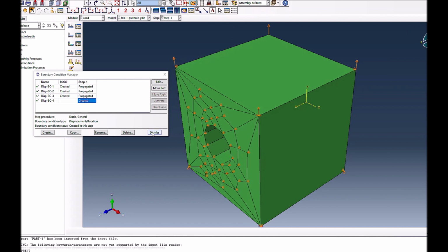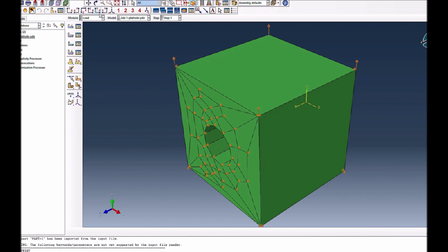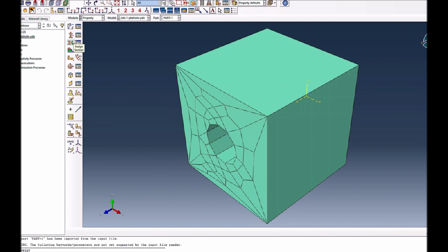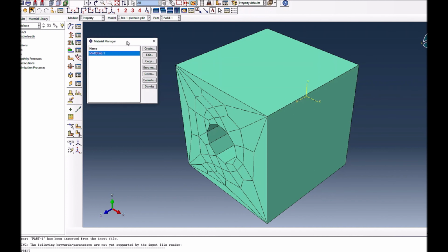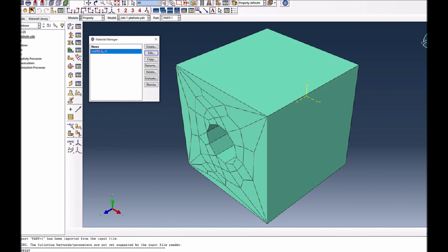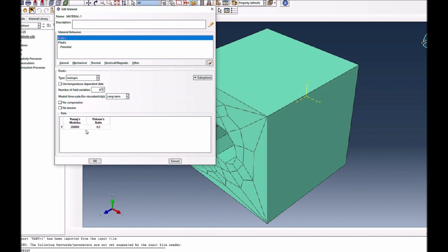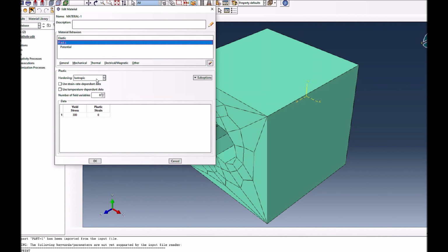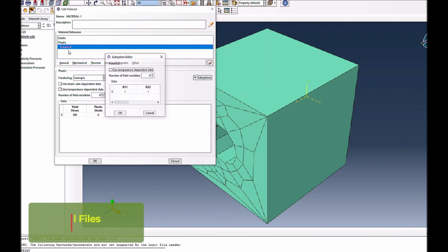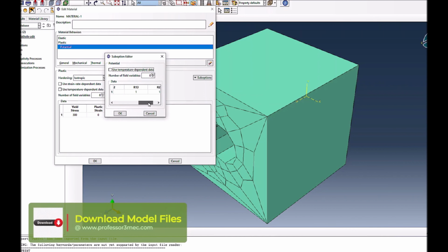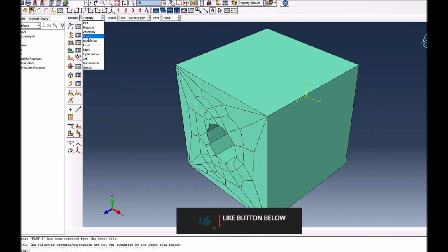So I think it was an easy surgery because I don't need to simulate anything, but just to show you what else is there, check everything is correct. Mesh, you definitely need a modification in that. Material property wise, it's an elastic material. Most probably it's in millimeters, so everything is in megapascals. Then plastic properties, which is ideal plastic, and there is a potential which has been used with these constants. Again, all are one. There are no other things stepwise.